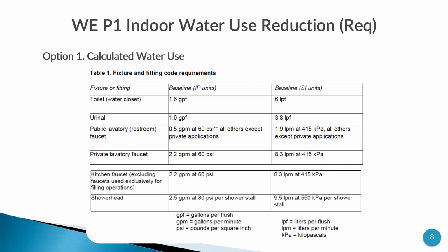Okay. Generally, what are we looking at? Say faucet, public lavatory faucet or private lavatory faucet. Say private lavatory faucet, you are talking about 2.2 gallons or 8.3 liters per minute, right? But generally, the normal faucet is almost 15 to 18 liters per minute of flush out that is happening. A normal thing that is available in the market, almost double of it.